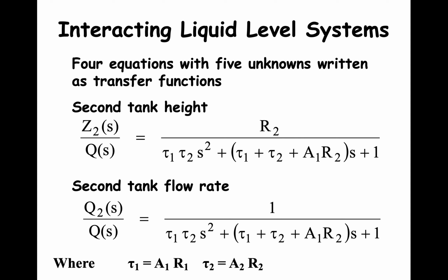This slide shows the transfer functions for the fluid depth in tank 2 over the inlet flow rate Q and the tank 2 outlet flow rate over the inlet flow rate. The transfer function for the fluid depth in tank 1 over the inlet flow rate Q and the flow rate leaving tank 1 over the inlet fluid flow rate Q are listed in the course packet on page 11-6. You will not need to develop these transfer functions, and you can just use them and reference the course packet.